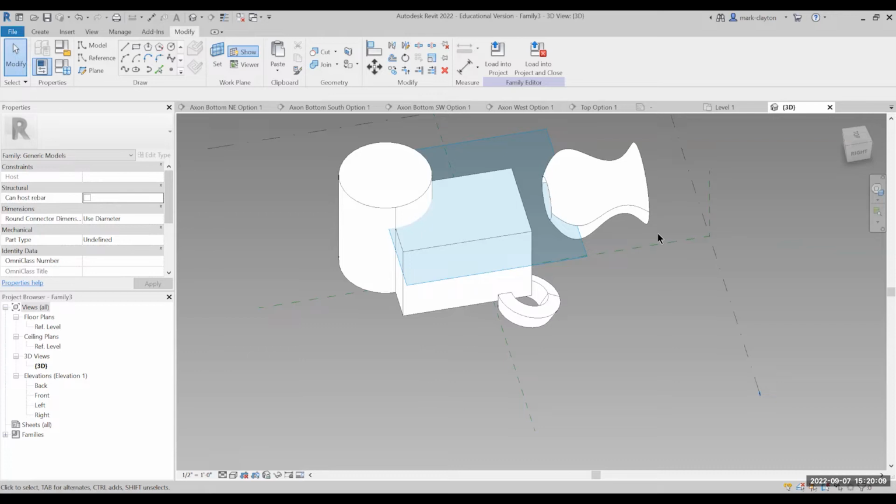That would be confusing. How do you revolve it around an axis and it starts intersecting itself? The mathematics go crazy. So that closed figure has to be on one side of the axis or another. It can have one edge right on top of the axis. That's okay. It just can't cross the axis. So, try making the surface of revolution there.